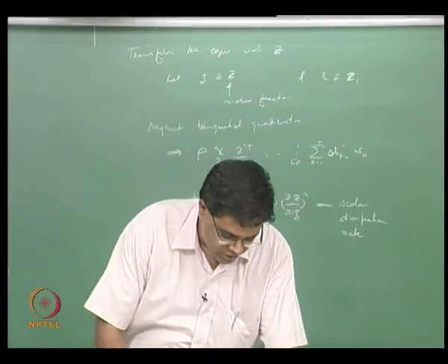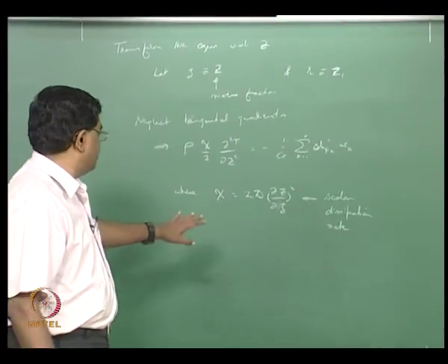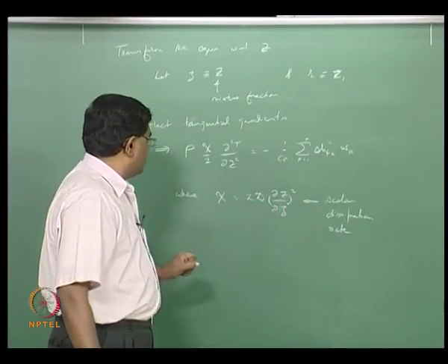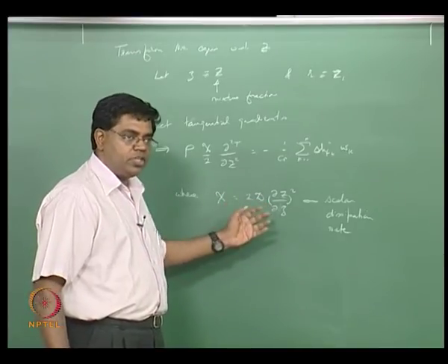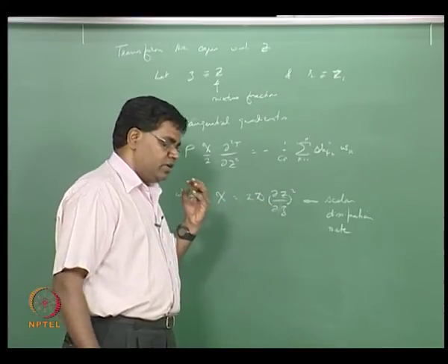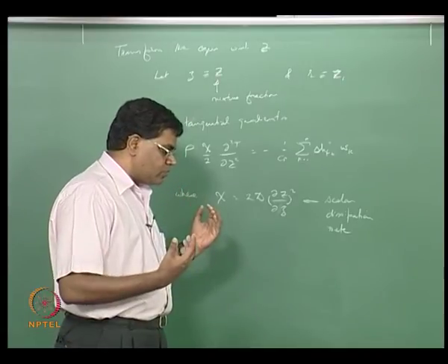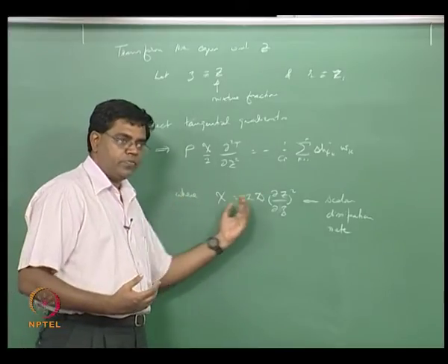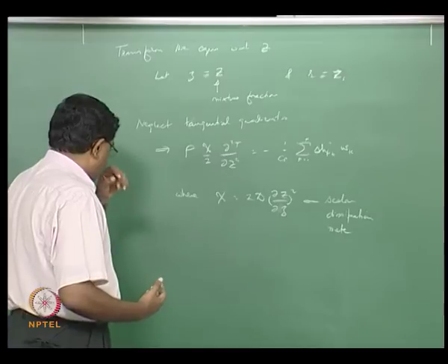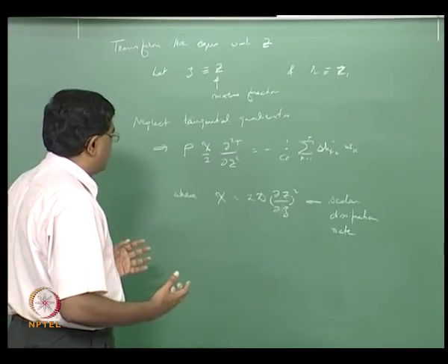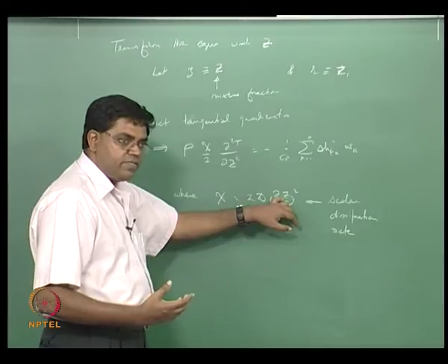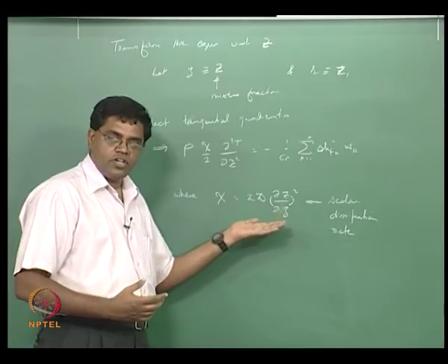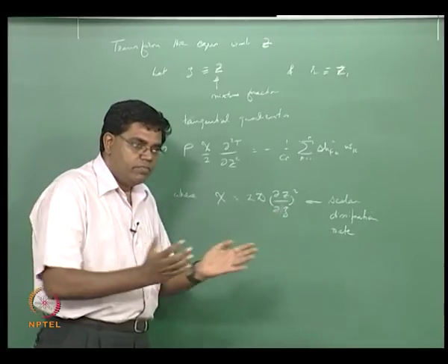And this is essentially looking like a diffusion term. In fact, the scalar dissipation rate has dimensions of 1 over time, and essentially it gives the characteristic diffusion time scale, right? And basically it tells us how the diffusion happens. Z is the mixture fraction, keep that in mind, and you now have the gradient coming into the picture. That means it essentially represents the transport phenomenon of mixing.